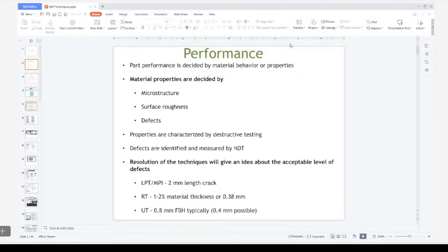First thing they will see is the choice of the material. Let's say I choose a steel, typically low carbon steel. Okay, what is its yield strength, its fatigue strength, and fracture toughness? The strength will help me to fix the factor of safety. Fracture toughness will tell me, even if I initiate the crack, what residual life I will get, whether the material is tolerant enough to have sufficient residual strength before failure or fail catastrophically.